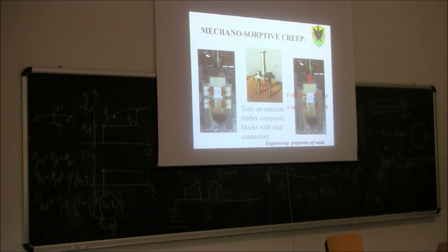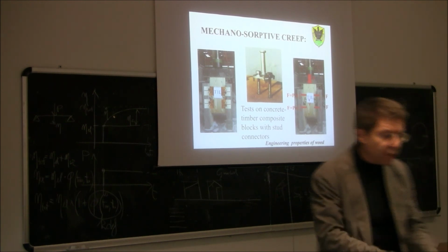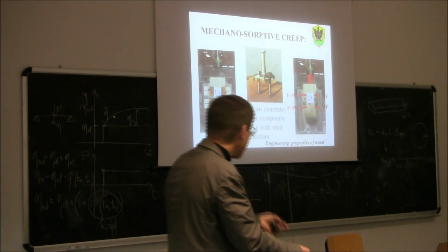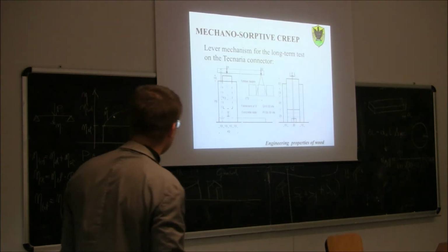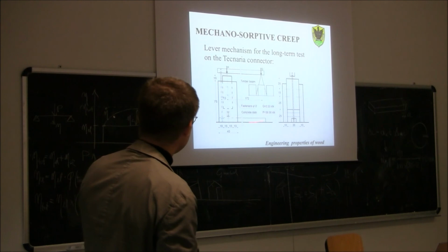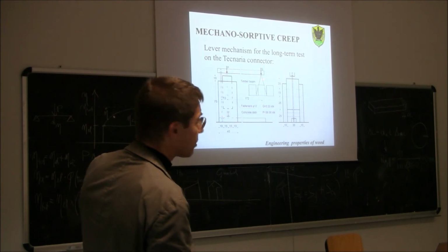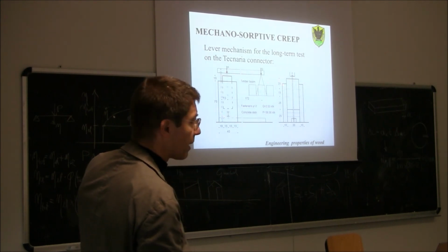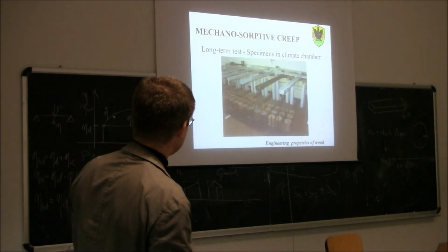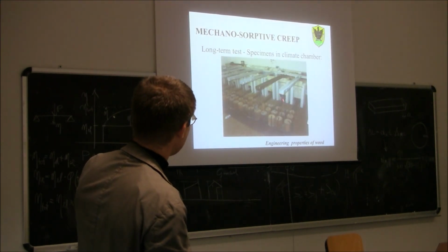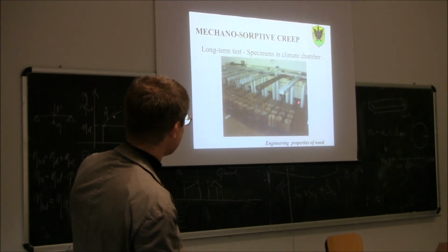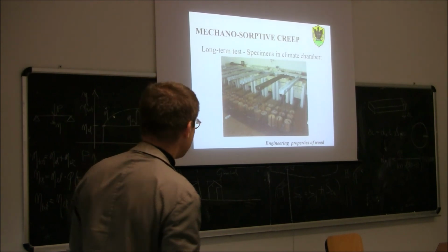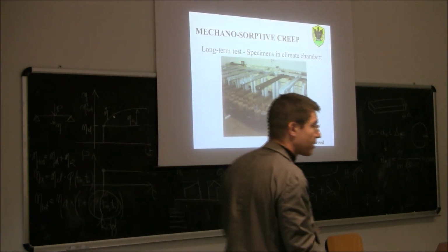When you connect timber with concrete, you can expect that this connection is going to creep over time. We were interested in this phenomenon of mechanosorption. So what we did, we applied a constant load over time with this lever apparatus. All the specimens were loaded in order to apply a constant load over time. This was inside the climate chamber.